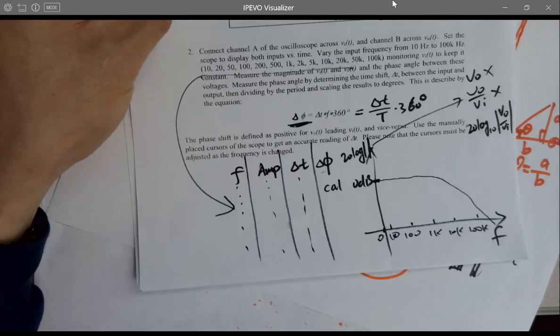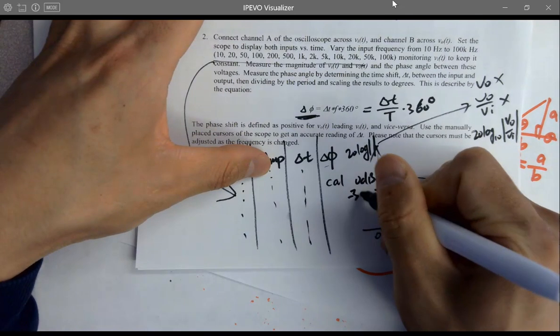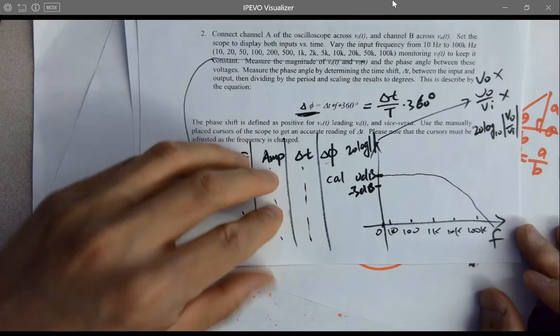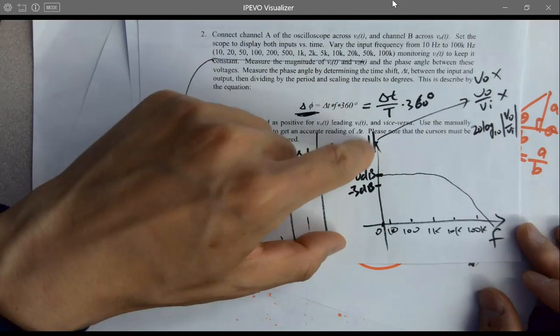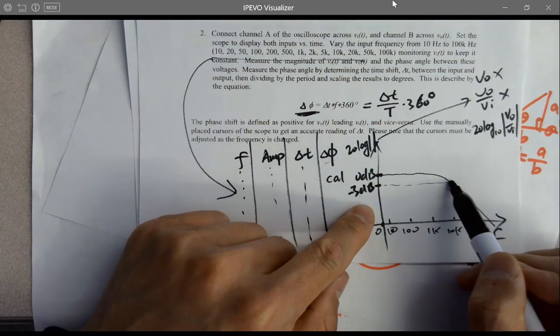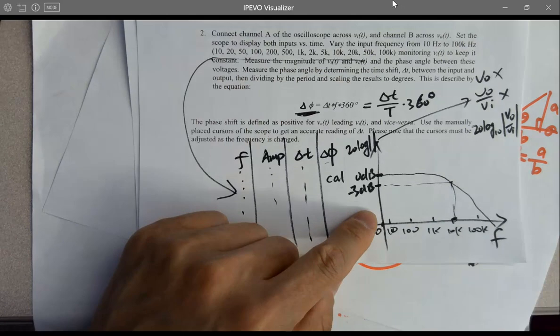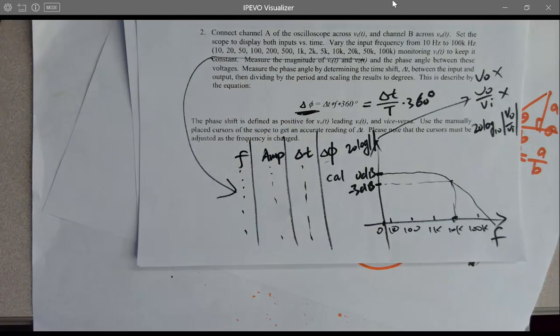Keep in mind, 3 dB frequency is actually minus 3 dB frequency. It's over here. So when 20 times log V over VI is minus 3 dB, you'll find out the plot here and try to locate that frequency, find out what's the frequency. It's giving you a minus 3 dB attenuation.